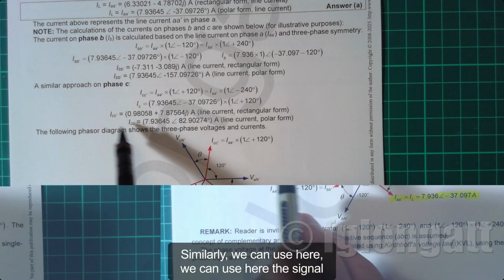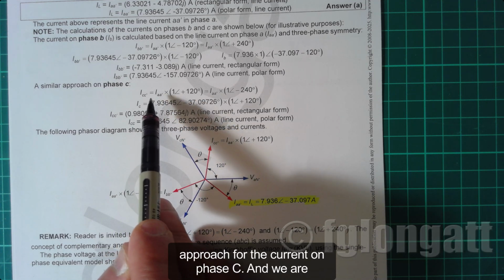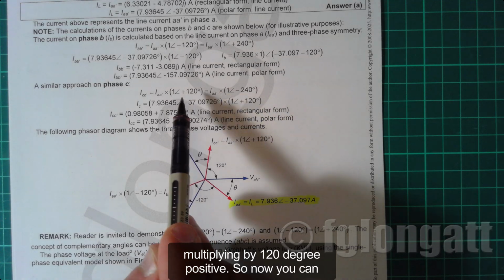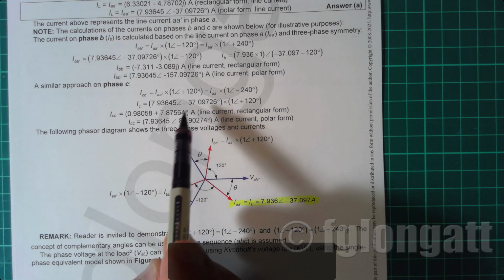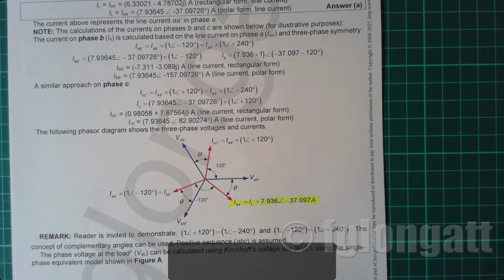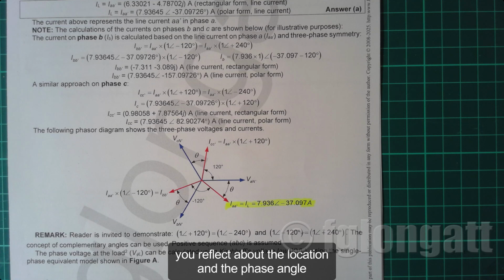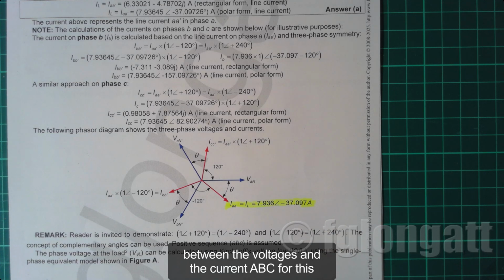Similarly, we can use the same approach for the current on phase C, and we are multiplying by 120 degrees positive. So now you can see the same magnitude, 1.93 amps, but the phase angle, as you can see over here, is 82.090 degrees. So again, my dear students, what I want is that you reflect about the location and the phase angles between the voltages and the currents ABC for this circuit, okay?